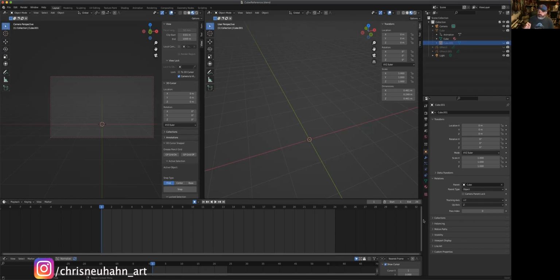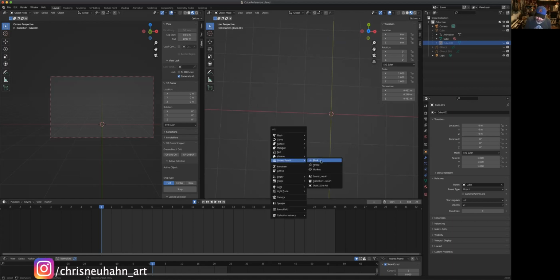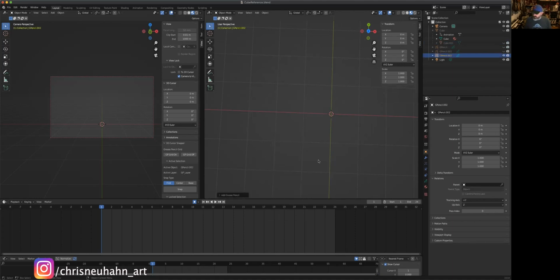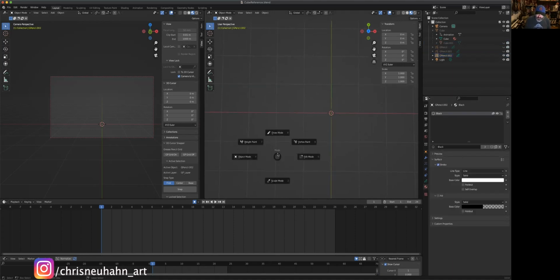So the first thing that we need to do is to try and figure out where our angles are, our slices out of the circle. So for that, I'll show you what I mean. And what I'm about to draw will actually come in very handy as you're thinking about these turns. So let me create a blank grease pencil. Switch to draw mode.